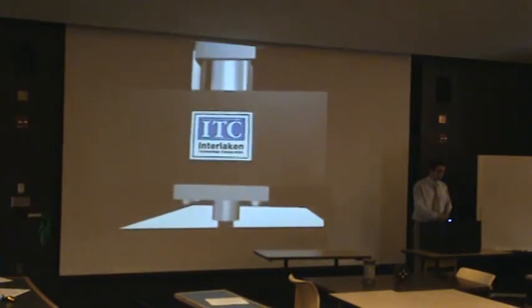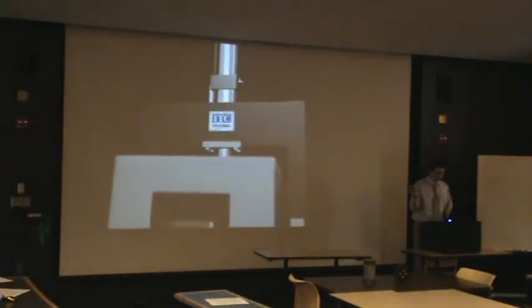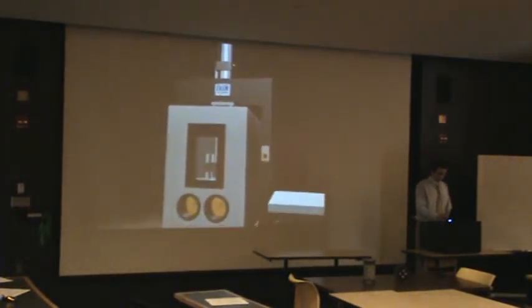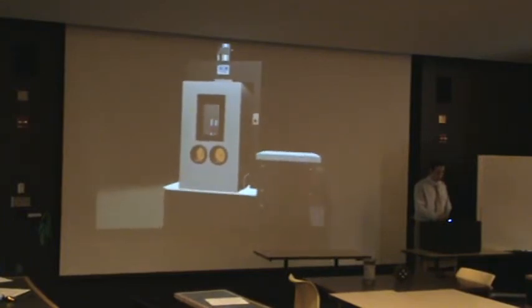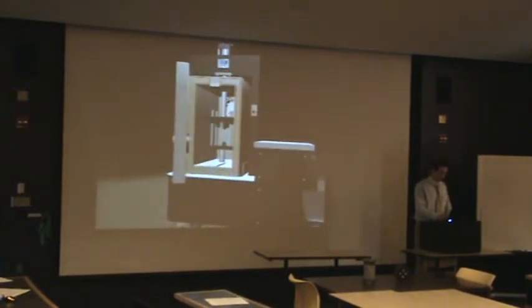This video is made by ITC. I just edited the video to be compatible with my presentation. This is the machine we used. This is a servo-hydraulic machine. Up here is a load cell to control the load, and this is a temperature chamber to control the temperature. Then this is the jig to apply the load.